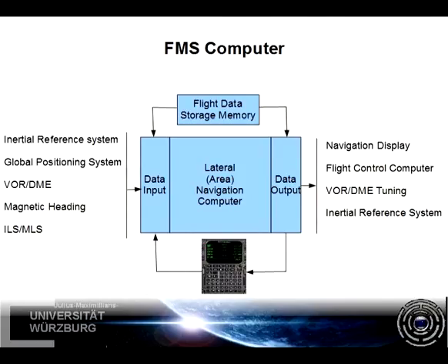Together with the navigational database that contains data on magnetic variation, airways and waypoints, approaches for all relevant airports and radio navigation aids, it is possible by means of data fusion to calculate a very good estimate of the current navigational situation and prevent the runaway of the IRS itself through a feedback. It is even possible to deduce the current wind by combining the data with the true airspeed vector that is determined by the air data computer.